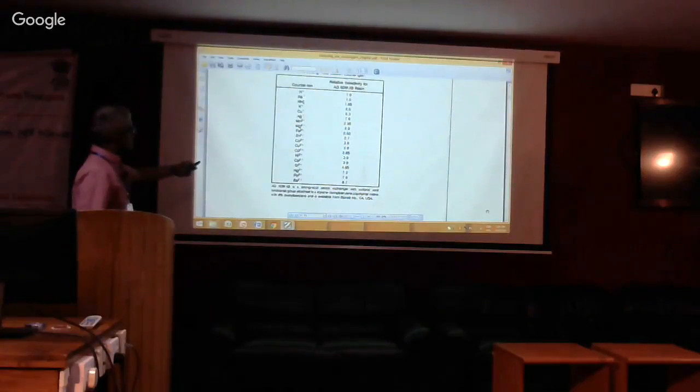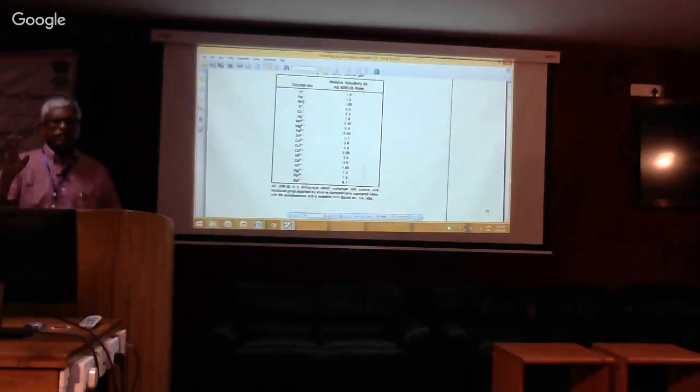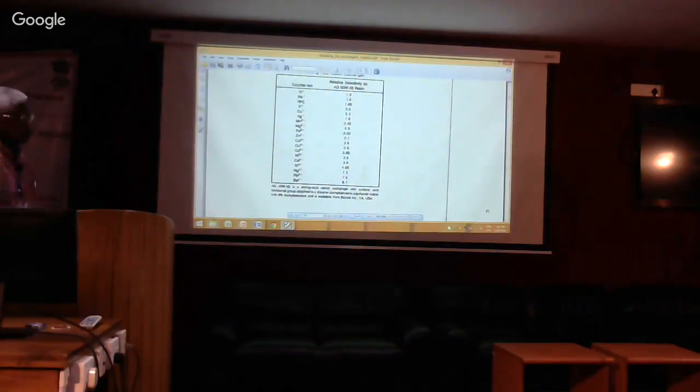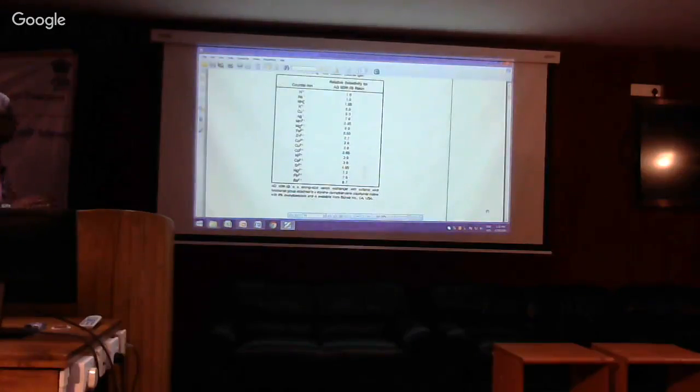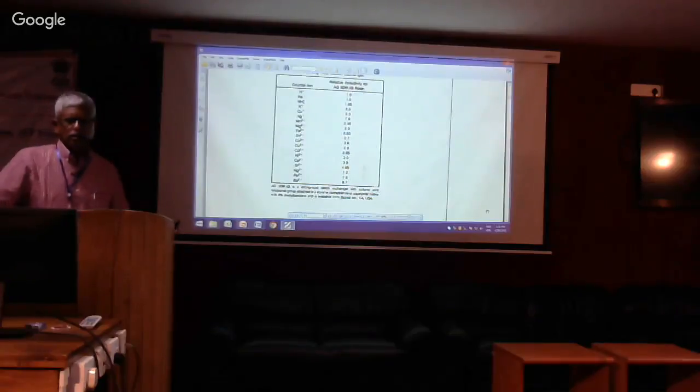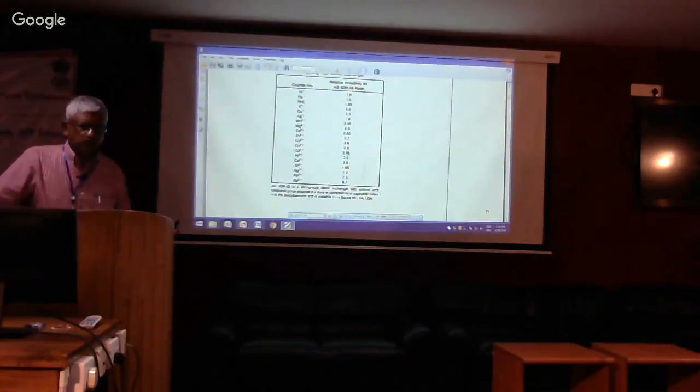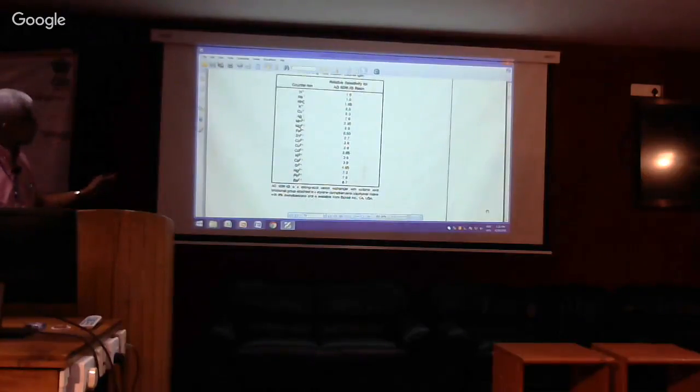I will bring this solution which has nickel, and nickel is 3, sodium is 1.5. So let's say you are able to do partial nickel removal. When this bed is exhausted, how would you regenerate this resin? What would be your ideal regenerant? NaCl, okay? Because it's a strong acid.